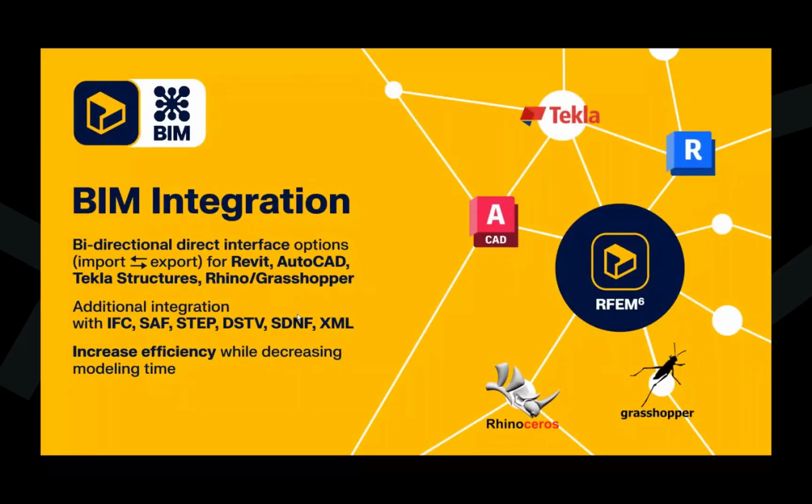We do offer a bi-directional direct interface option. So we can import, export, and round trip between the programs listed here, including Revit, AutoCAD, Tekla, Rhino, and Grasshopper. The reason I listed a direct interface is that these two programs are speaking directly to one another locally on your computer. We're not sharing some commonly shared file extension between the two programs to exchange data; rather, those two programs are directly exchanging data together locally on your computer.